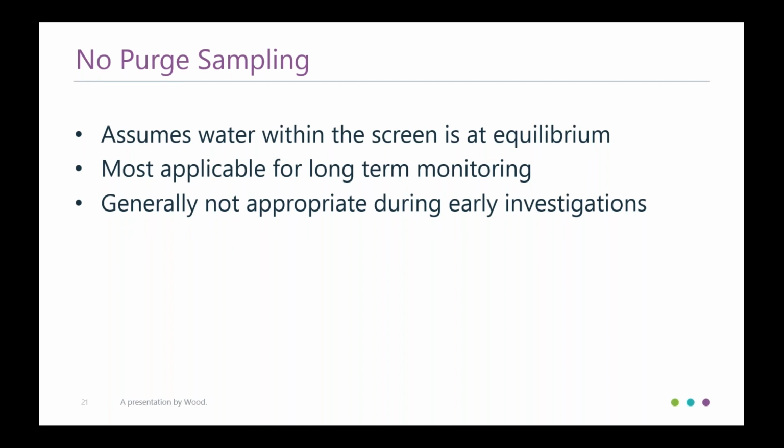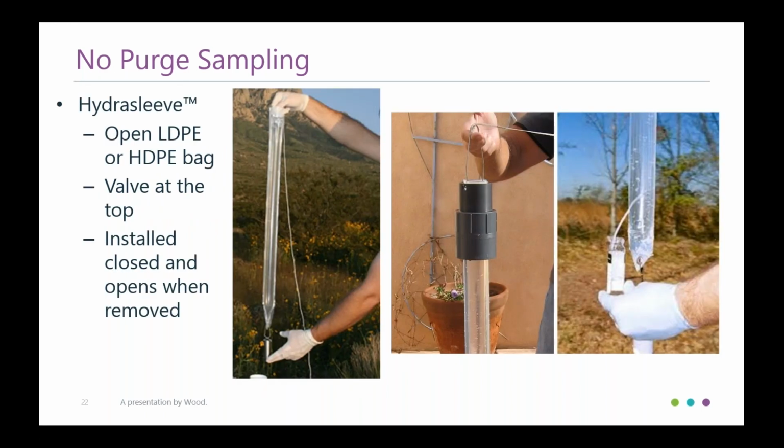During early investigations, there may be reasons that you use these. If you have a well with a long screen and you want to see if there are contaminant gradients, you might want to put in some of these samplers, which I'll get into here.